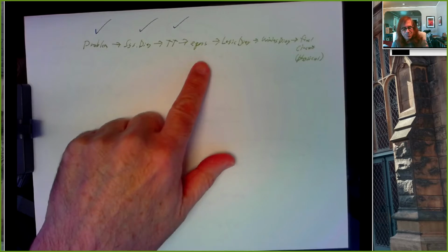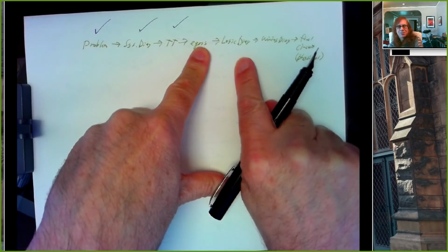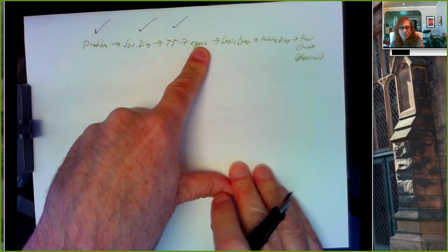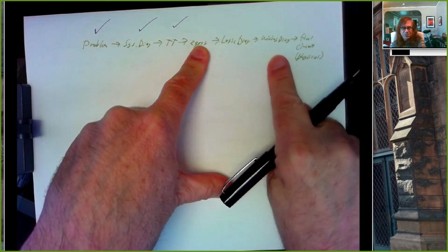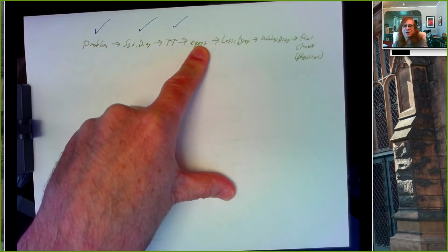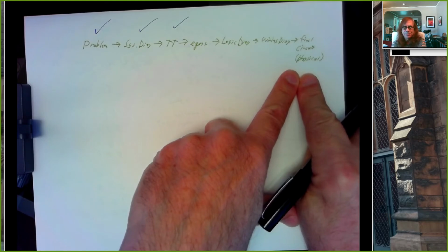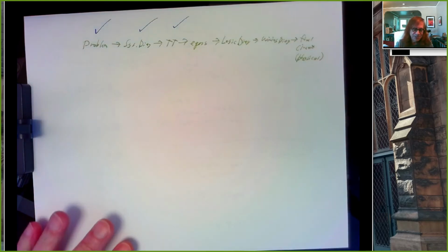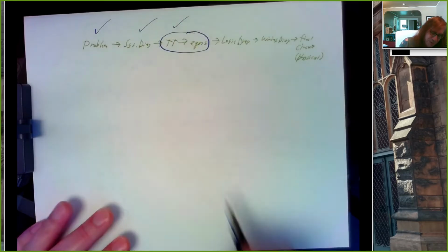Once we have equations, going from there to a logic diagram is very straightforward. That's the mechanical procedure we went through quickly last week. Then from there to a wiring diagram is picking parts out of your parts container, with power on this pin and this input going here, and so on. And then it's plugging the wires into holes on the board, or dragging and dropping in Tinkercad. So this is where most of the work comes.